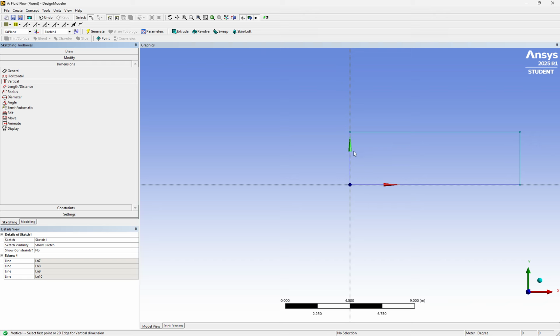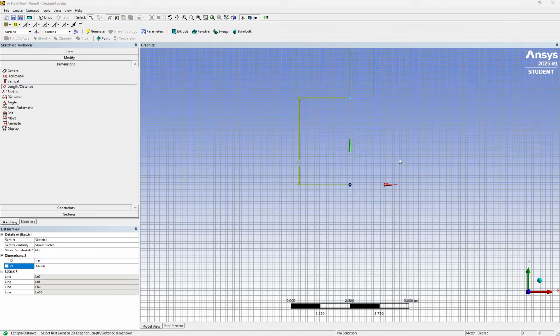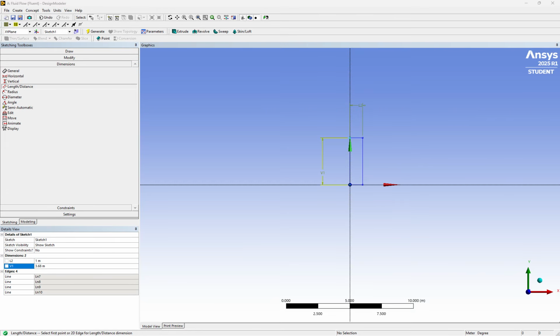Then I should assign some dimensions here. When we do a 2D geometry, anything on the x-axis will be the work on the 2D geometry. The work will be done on an XY plane. So now what we have is this configuration, the solution domain. The bottom line here will be our plate, and the length has to be 1 meter. Here is going to be the air that's going to be simulated, and the left side is one boundary, the right side is the other boundary, and the top surface is my third boundary.